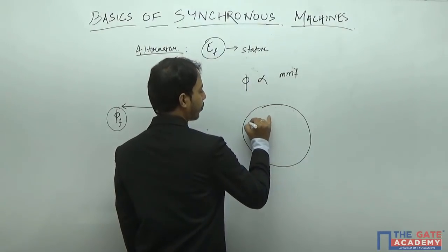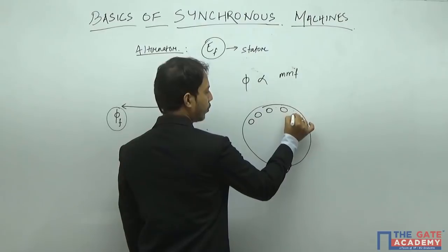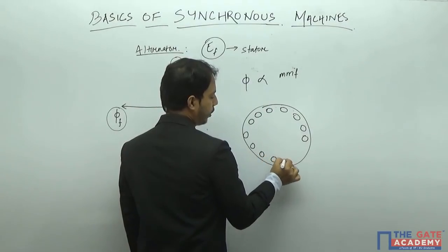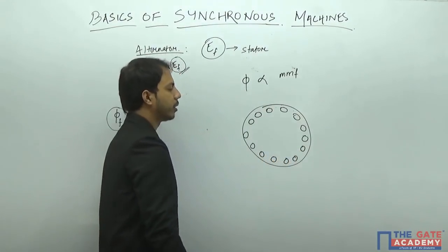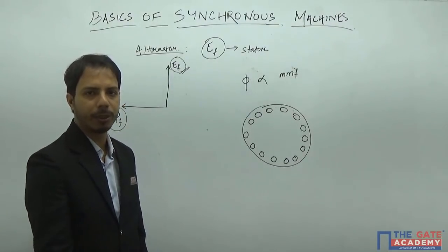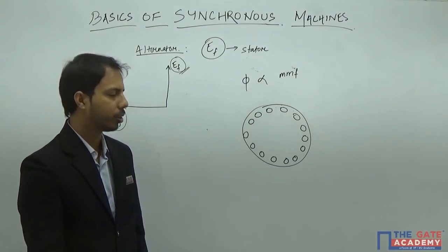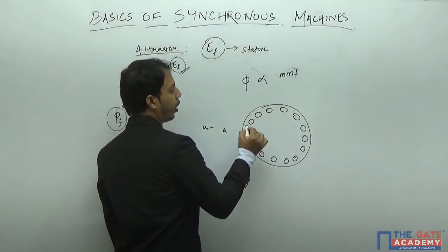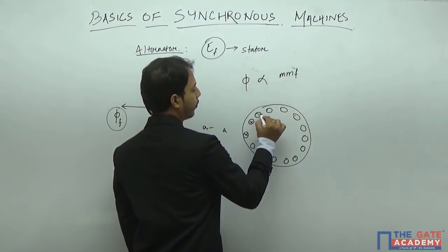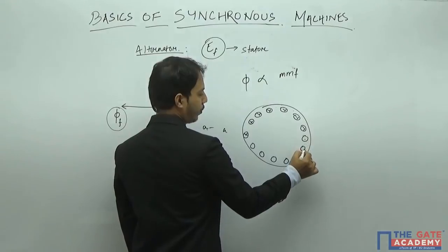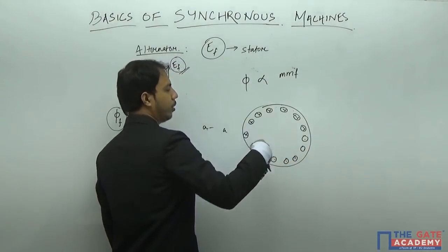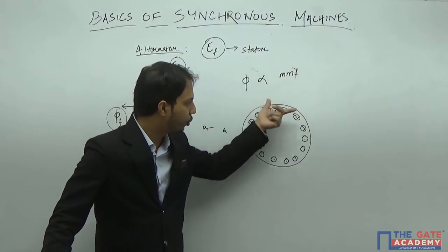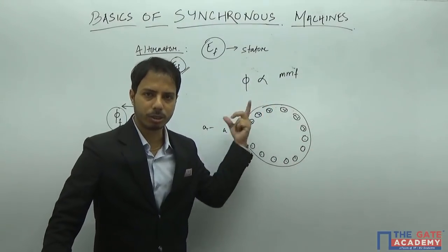That means this particular situation is called distributed winding. So I have distributed the slots, one slot into many slots. So what happens is, now suppose I have a coil A dash. So I put it in various parts. So I have wound it in various ways. What I have done is I've spread it throughout the cross section.